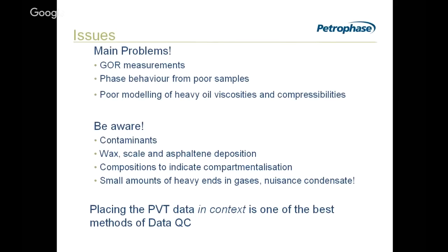It's very lean condensates. These can be really troublesome. It's very hard to measure the amount. It may be below the meter range, and yet we've got to deal with it. You can't just ignore it. It'll accumulate in pipelines. So how do we configure our test to try and get more liquid out, to get a better handle on it?